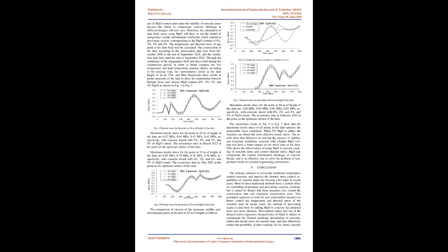In this study, the calculation model parameters are referenced from V. Nguyen [32]. Fig 3. Three-dimensional geometric characteristics of the Linxihe arch dam. B. Analysis of the effect of MgO content on thermal stress field. In this section, the dissertation will analyze the ability to improve dam body stress with different MgO content. The use of MgO content must meet the stability of concrete dams because the ability to compensate concrete shrinkage in different dosages will also vary.